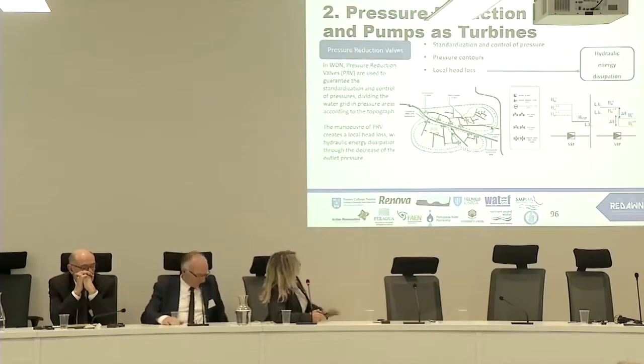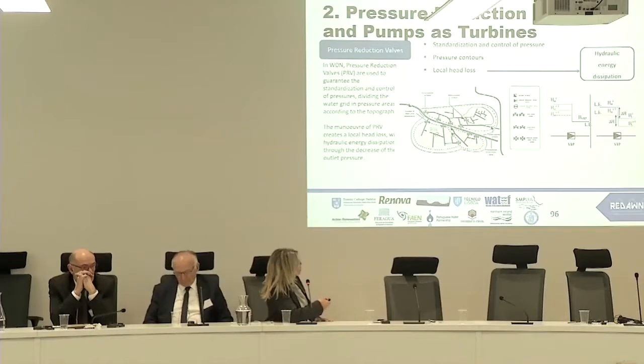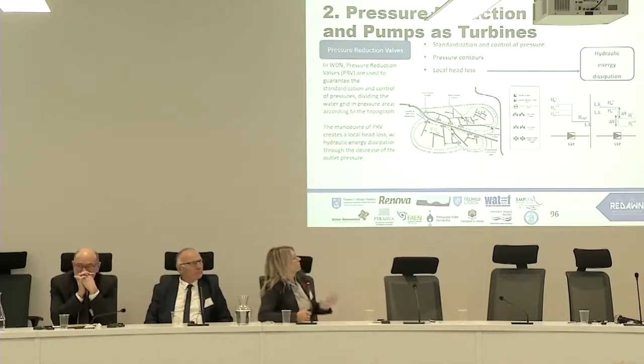The maneuver of a pressure reducing valve creates head loss. And if you look at the characteristic curve of a valve, pressure reducing valves or control flow valve, it is quite similar to the characteristic curve of a turbine, or a pump-as-turbine, or any type of energy converter using water.